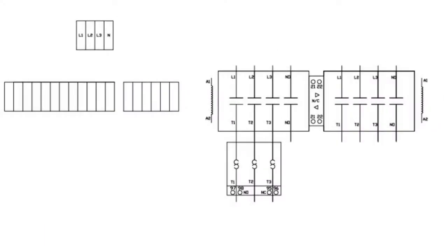Actually, before we move on to the next diagram, let's take a moment and look at what we're going to be using for our wiring diagrams this term. What I'm showing you here is the template that I will provide you, and you will be filling in all of the wires that connect to all of these locations. Up there in the top left, you can see line 1, line 2, line 3, and neutral. That provides us with all 3 phases of a 3-phase AC circuit.